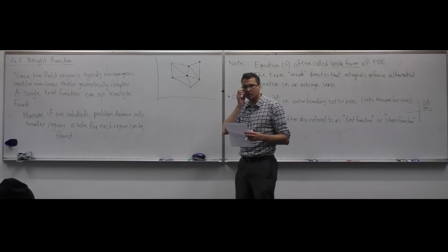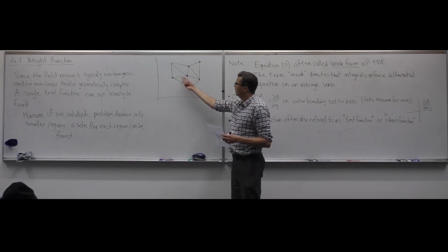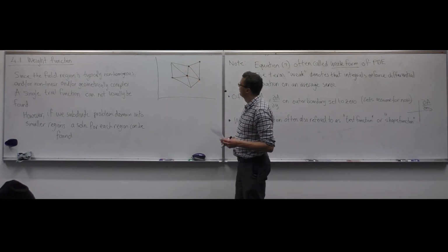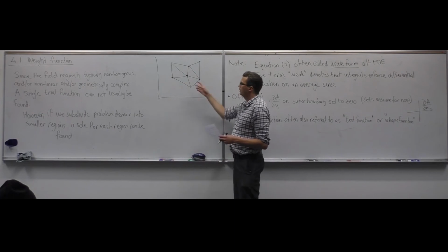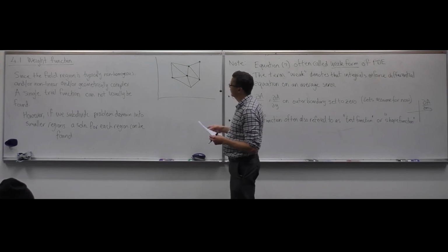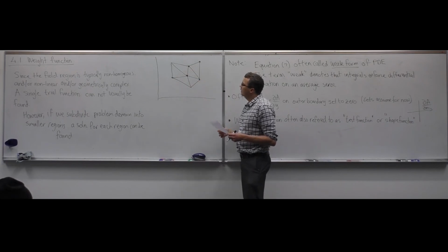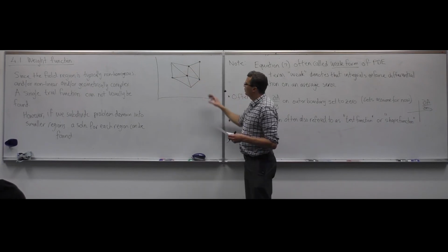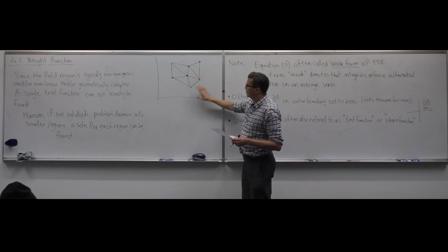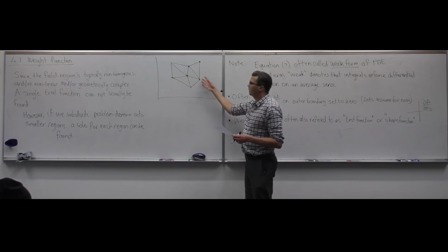You know how we solved the coefficients just before, and we had 2 unknowns. So you could think we'd have a trial function with 2 unknowns in each of these triangles, and then we have to determine the solution. You can see where this is going, probably. This would become rather difficult to do on the blackboard, but it's a piece of cake for a computer to solve lots of unknowns. So the way to do that is to break this problem down and put it into matrices and then evaluate them. The process to do that, I'm going to outline.